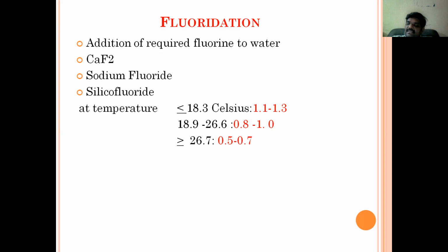Understand? I said why we should add. Simply to get back the concentration, or else, as it is the essential element, we are adding fluoride. How much we can add? Simply 0.5 to 0.7, as we are in the country where the temperature is about 26.7 degrees.